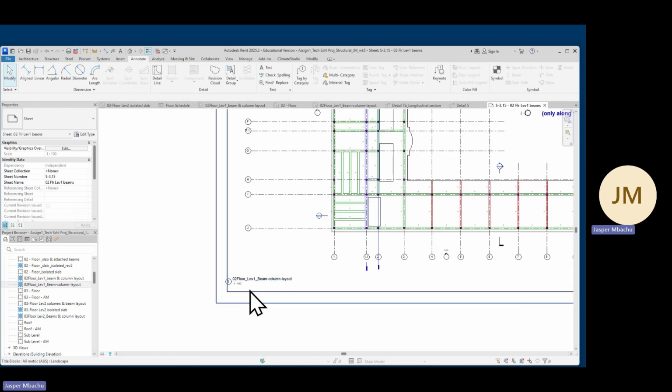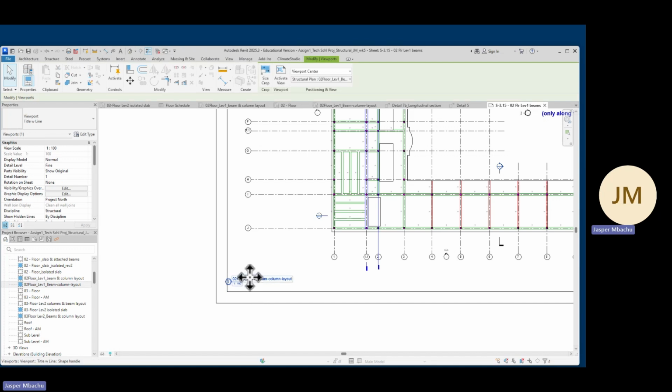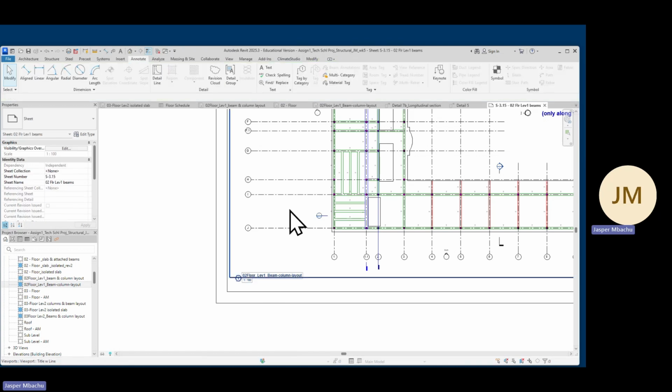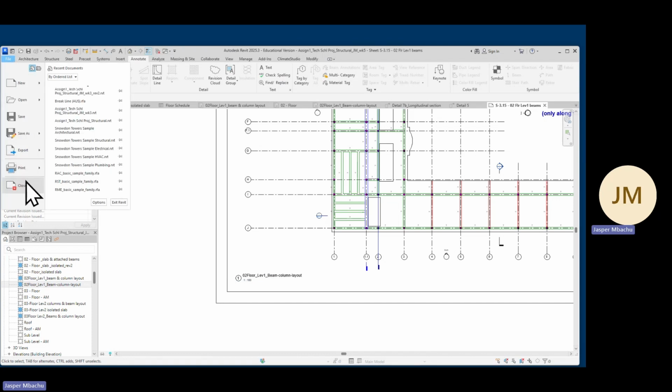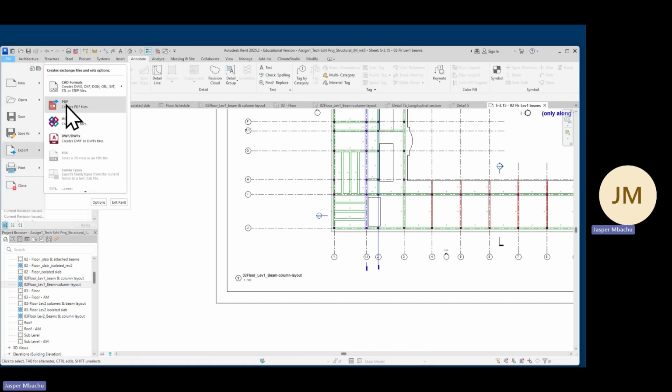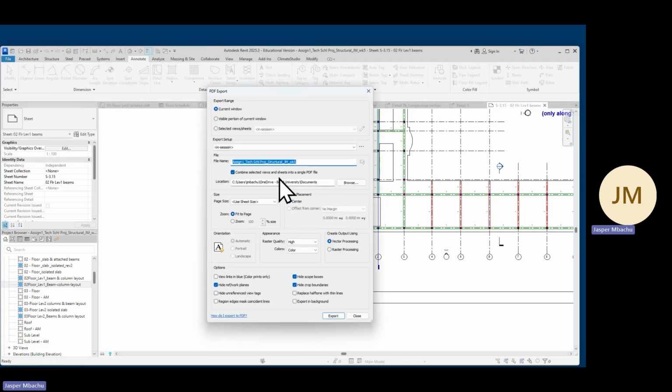if yours is within here, if this line is within here, click on it. When it is selected, then use your arrow key to make sure that it is fitting well. And then when you go back to this drawing, you can do the rest of the dimensioning. And then it's time for you to export this now. So you click on File and Export as a PDF. And you give it a name first. You say is 03.